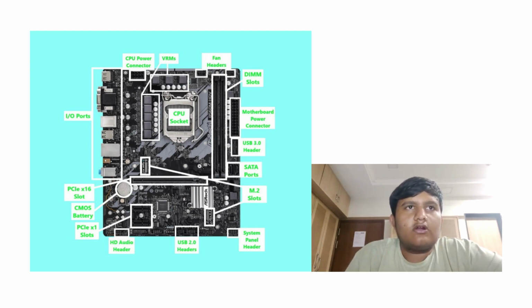Modern CPU sockets and processors are based on the Pin Grid Array, PGA, architecture. A PGA is a type of packaging used for integrated circuits, IC, such as a microprocessor. It is basically a square with pins that are organized below the packaging. Pins are spaced approximately 0.1 inches, which is 2.54 mm, apart to cover a portion or the entire underside of the package.